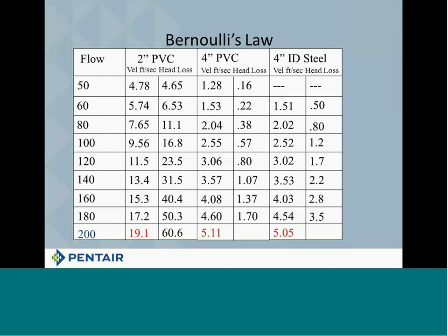And I don't think anybody without real special equipment is going to be able to tell 0.061 of a foot per second. All right? Now, the point that we're making here is that as long as the ID of the pipe is the same, the velocity is going to be the same. But the type of pipe does affect what we call friction loss.